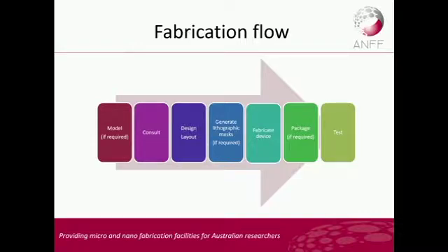And ultimately what we want to get to is a point where we do a layout. And basically a layout is just a pattern that we're going to put on a photolithography mask, and we might have one, or we might have 2 or 3 or 4 masks in order to build up a particular device. Then we're going to generate the lithographic masks, and then we're going to fabricate the device. We'll go through that cycle of photolithography, deposition, and etching.